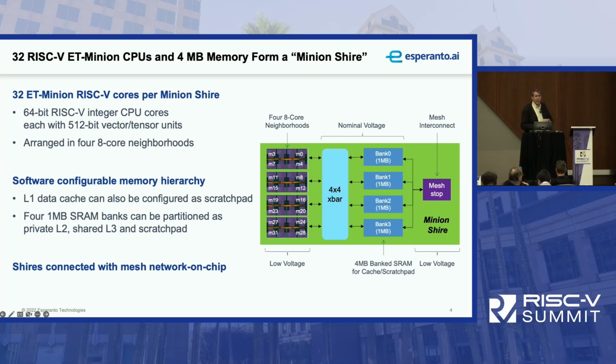Okay? Now, in order to save power, we run the power-intensive parts, so say the vector unit and the RISC-V core, we run them at a very low voltage. So what we do is design as if we were designing a 6 or 7 gigahertz processor, but instead of trying to run at that really high speed where things are inefficient, we run it at sub-gigahertz ranges, but at very, very low voltages.